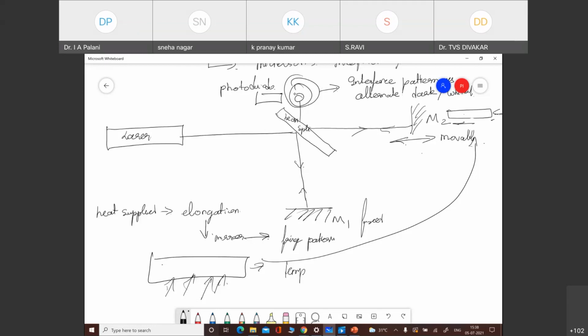Like one experiment which we did in our lab. We had a small pressure vessel. In this pressure vessel, we kept two different mirrors and this system was kept over here. By just pumping the pressure inside, this entire system was getting elongated. When the entire system was getting elongated, obviously it gives a certain amount of deflection on the surface. With respect to the deflection, the mirror gets displaced, which causes a variation in the interferometer, and which also gives me better clarity about how much pressure is being built on this surface.